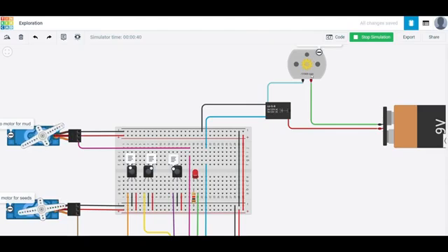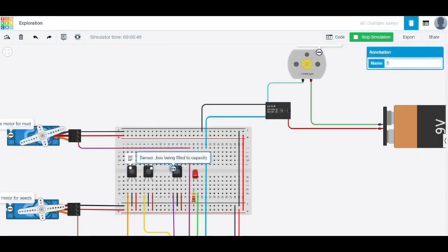As the drum is rotating at a high speed, the seeds get covered by the mud, forming a clay ball. These balls fall into the collecting tray where the IR sensor checks whether the tray is filled to its capacity or not. Suppose the tray gets filled to its maximum capacity, the machine stops working. That is, the LED stops glowing, the servo motor stops sweeping, and the DC motor stops running.